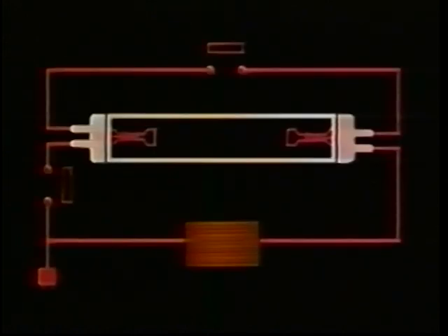The ballast is an extremely important element in the operation of any fluorescent lamp. The most common ballast is the inductance type, which uses a magnetic choke coil to limit the current supplied to the lamp. This circuit diagram shows a very simple ballast system for a preheat manual starting fluorescent lamp. Power is applied to both ends of the lamp. One switch controls the current through the starter circuit, while an on-off switch controls the use of the lamp.